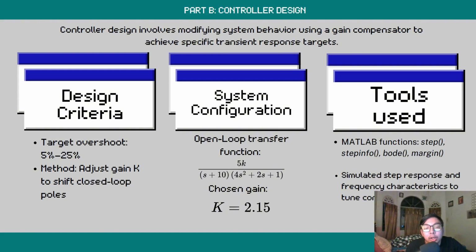The tools that I use to simulate are the MATLAB functions stepinfo, bode, and margin, to simulate step response and frequency characteristics to tune the controller.